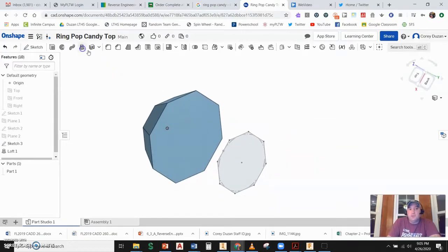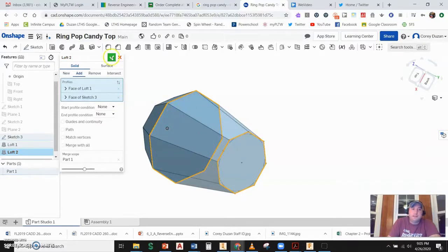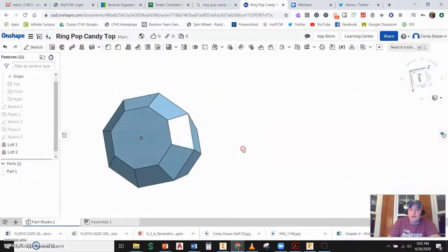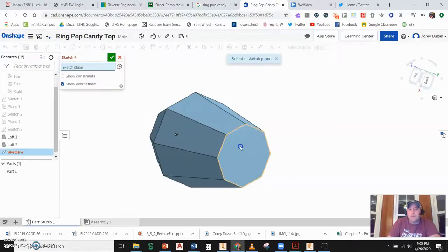Alright, so I'm going to come in here and do a loft. Okay, that's my first profile. That's going to be my second profile, and it's going to go out there and create that top candy part. All right, so that's done. Now I'm going to sketch on this face here.